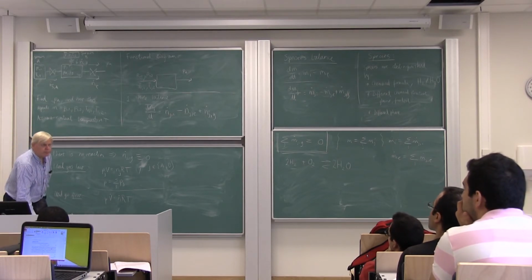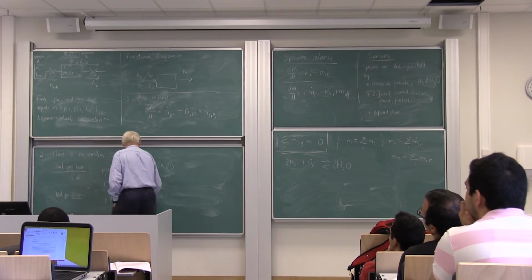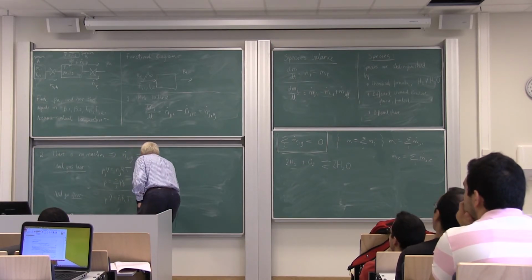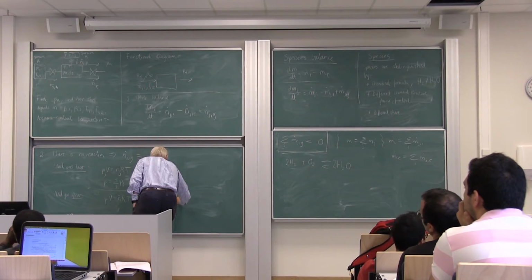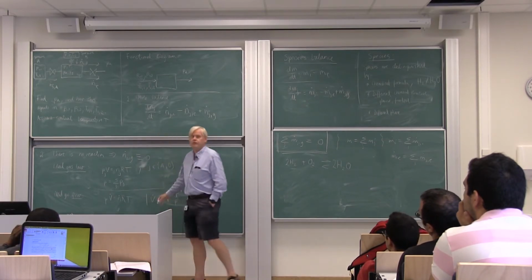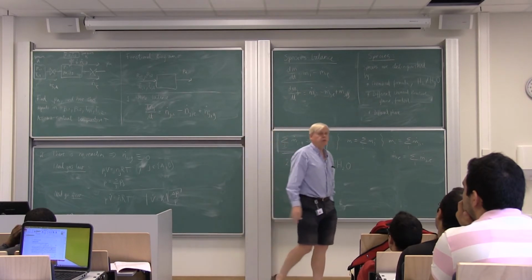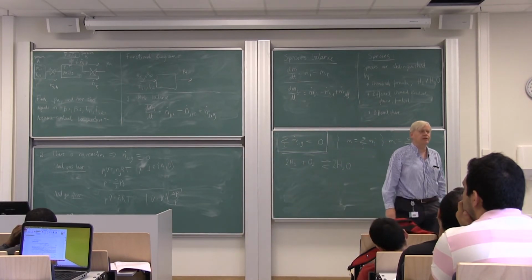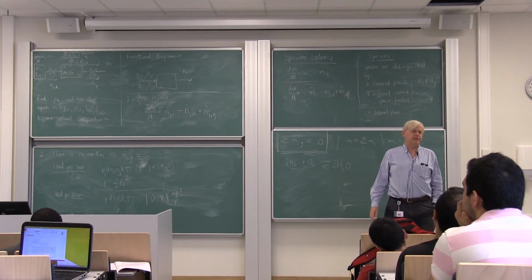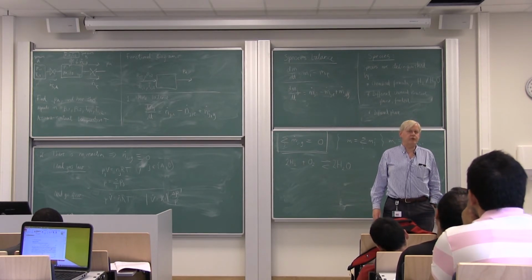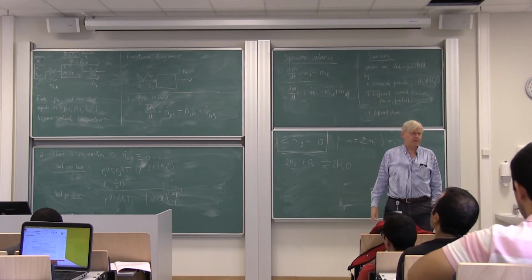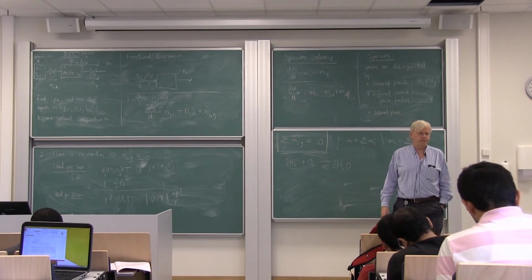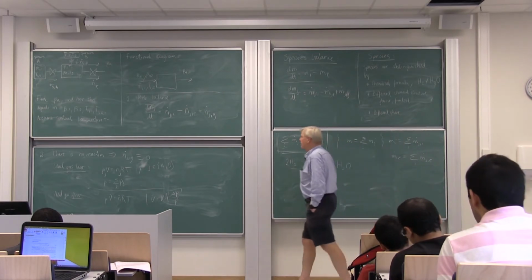So what is a possible expression for that? We will use this kind of standard expression that I've used in the past for mass flow, but we will pretend it's valid also in this case. The idea is that there is no flow rate unless there is a pressure difference. If the pressure is the same on both sides of the valve, there is no flow. Okay?